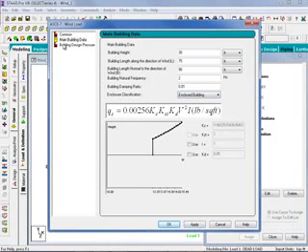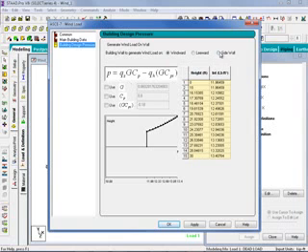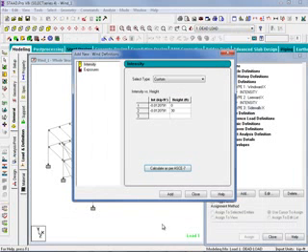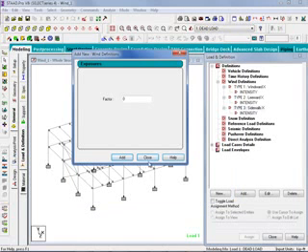This time, when I select my main building design pressure, I'm going to select the sidewall radio button. I'm going to click Apply and then OK. And then to officially create this definition, I'm going to click Add, and then again I'm going to just click Close.